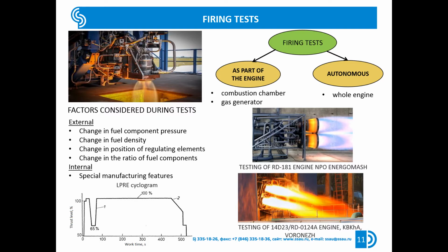The uniformity of the temperature field in a gas generator plays an important role. It should be noted, however, that for high thrust engines with a high pressure in the combustion chamber, the creation of such test benches can be very expensive. The main type of firing test is the assembly test of a liquid rocket engine.